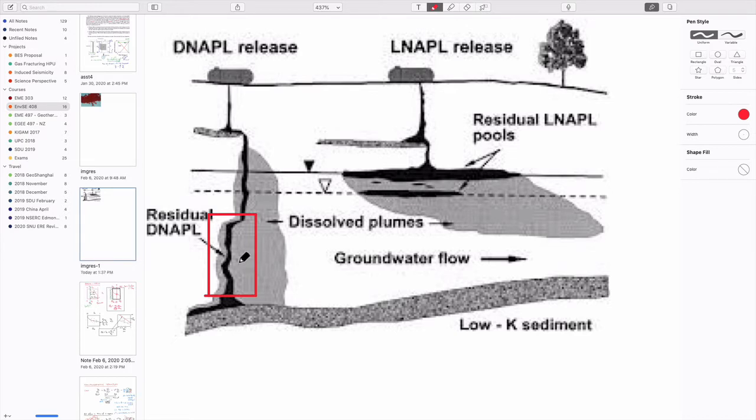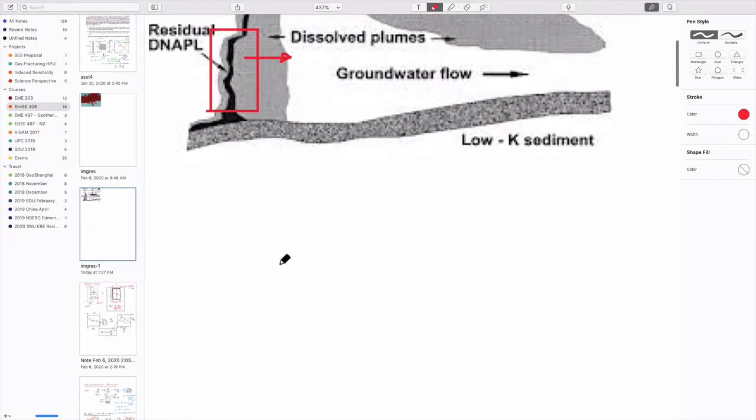So that was the first topic we dealt with, and we can calculate the rates at which fluids will move as fluids themselves. Then we spent the last little time from section 3 onwards talking about the rates at which components will dissolve out of this and travel down gradient driven by groundwater flow and dissolved in water. And we've divided that into two formats: conservative flow, where everything remains in solution, nothing comes out and sorbs onto the solids, and non-conservative flow, where sorption occurs, and as a result of that there is some kind of retardation.